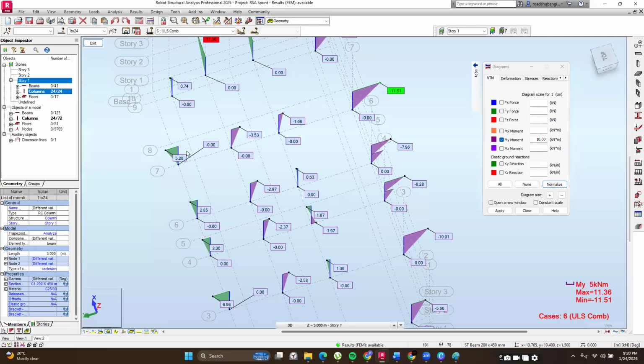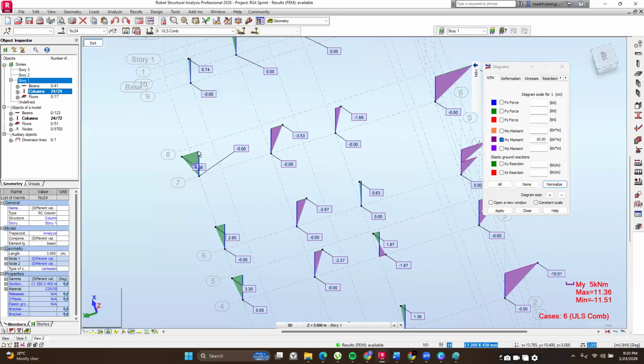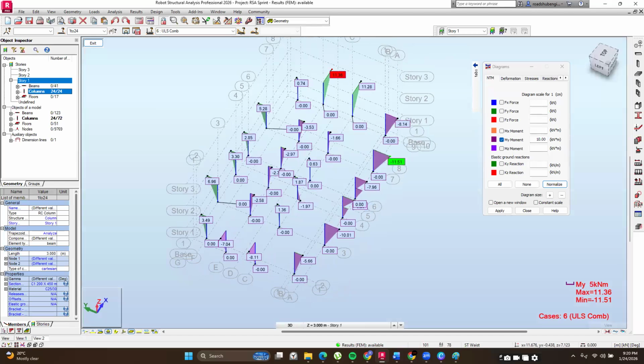If you remember the Hardy Cross method of distributing moments, you have a few elements that you are distributing moments for, and in a realistic way, you have no element on the left side trying to counter out the moments. So this is something you would want to look out for.